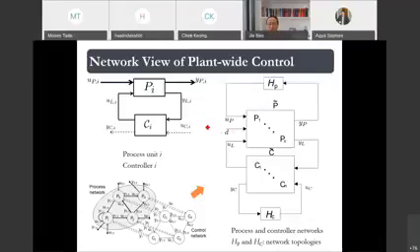Also, for the processes, we have another input, which is disturbance. The disturbance goes into different process units. HP is a topology matrix representing which output from which process unit is connected to which input of another process unit. And HC is a topology matrix of the controllers. It is very similar, and it basically says which controller is talking to which controller.